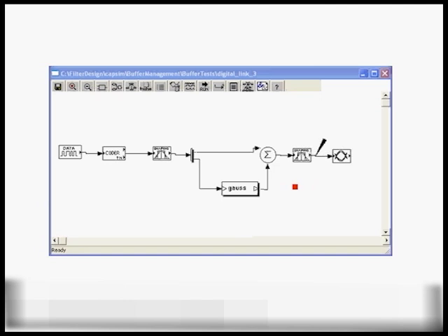And this also plays within the use of hierarchical blocks. For example, hierarchical blocks are visited and all of their samples are consumed until there's no more activity within that block, and then the higher hierarchical blocks are visited and so forth. So in many cases, you can actually control the efficiency of a simulation by grouping blocks within a hierarchical block.